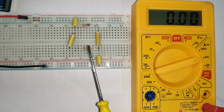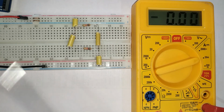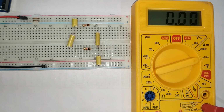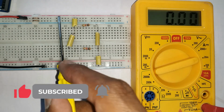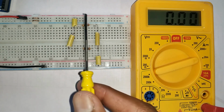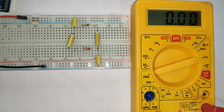So the current flowing through this resistor is 5 milliamps and through the other is also 5 milliamps. So the total current becomes 10 milliamps and we have verified our KCL here. KCL states that the incoming current should be equal to the outgoing current. So our incoming current from the supply was 10 milliamps and it gets divided into the resistors such that it follows KCL. We have done the practical of KCL.